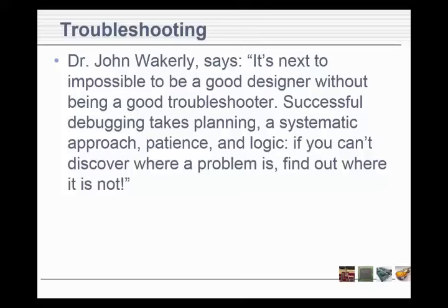Another thing that a lot of students don't see is I used to work in this area too, and what I'd do is I'd go to the middle of the schematic, and that's where I'd first test and see how many of these signals are correct here in the middle of the board or in the middle of this design.